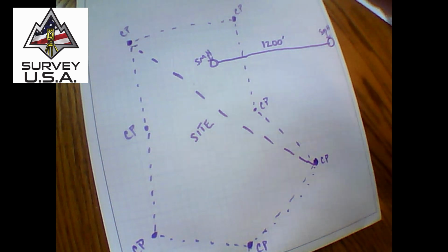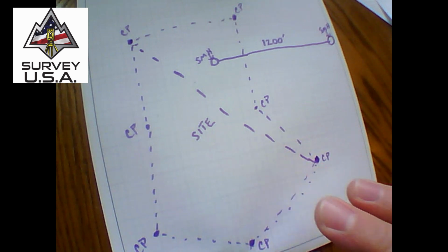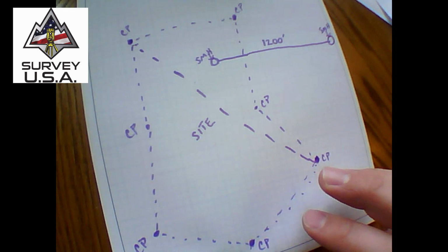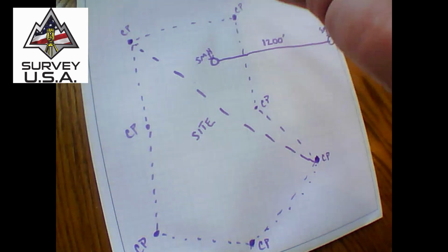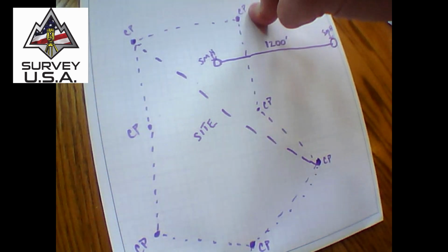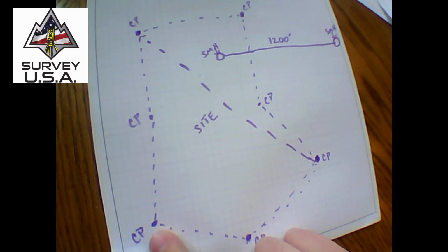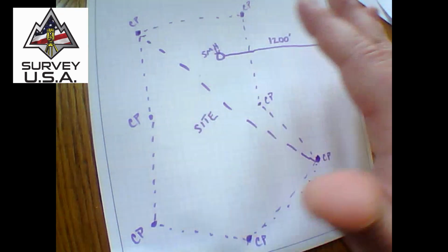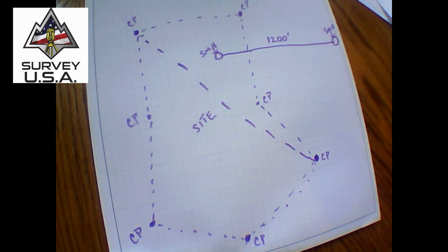Vertical hits good. The reason I do that is you don't know how the control was established. Yes, it all has published elevations. However, if it was all established with GPS to begin with, you're going to have vertical error in every single point, and they could go opposite ways. If you're 500ths lower here than you should be, and you're 500ths higher over here than you should be, you've immediately calibrated with a 1/10 of error in your site, plus every other point that probably has error introduced to it as well. That's why I do 1.